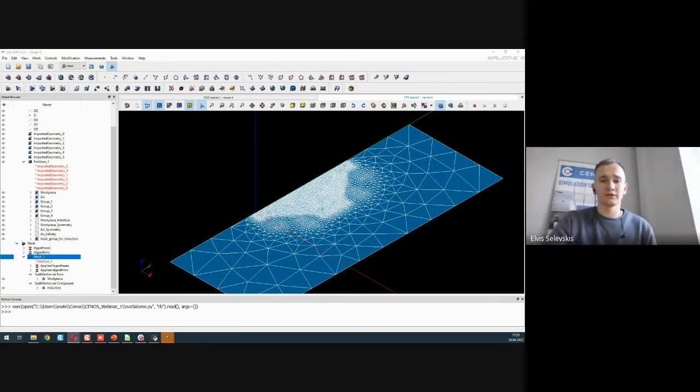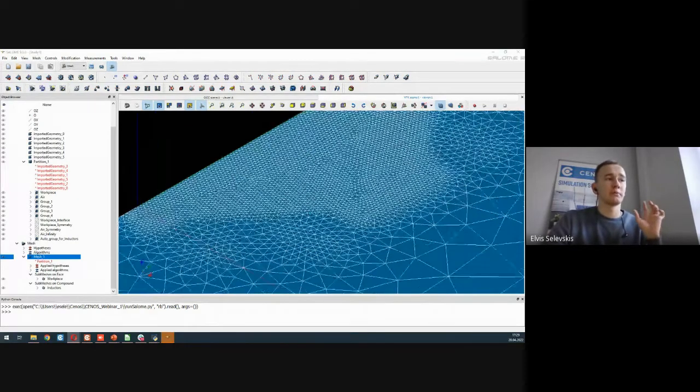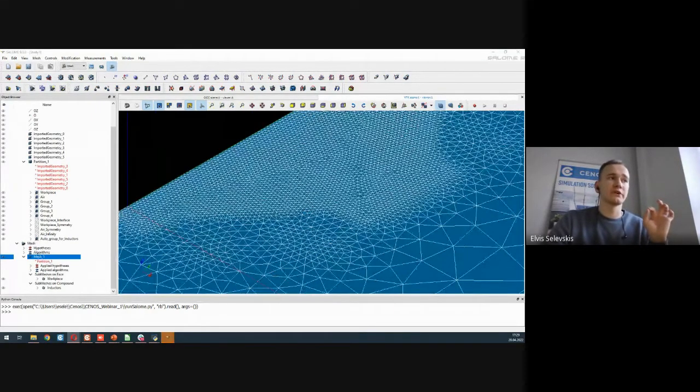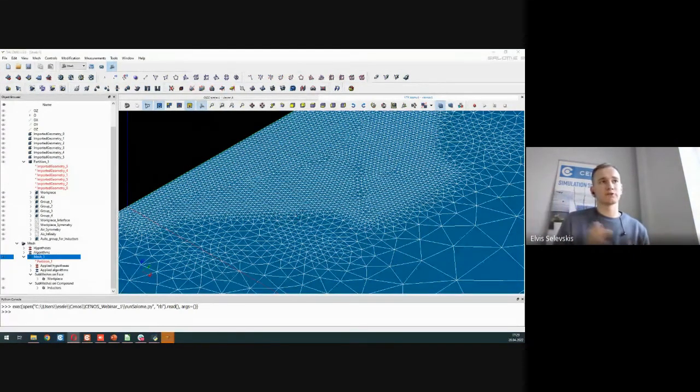So to take into account the skin effect, we need to actually make kind of like a smaller, maybe even thinner mesh objects on the very surface of the workpiece. So depending on your frequency, the material you're running, we get the correct current density, and the current gets soaked up nicely into the workpiece.